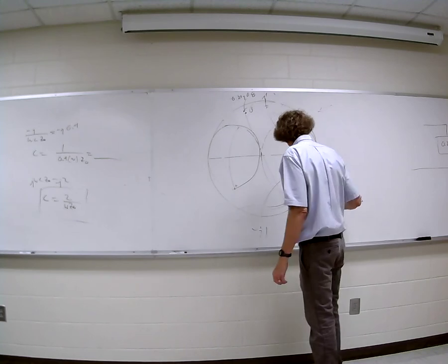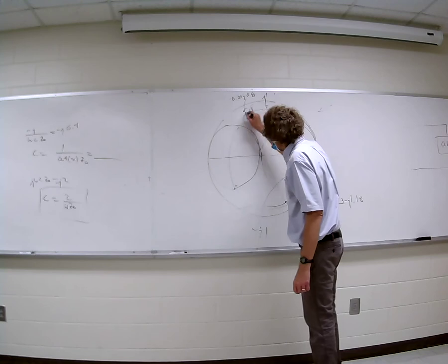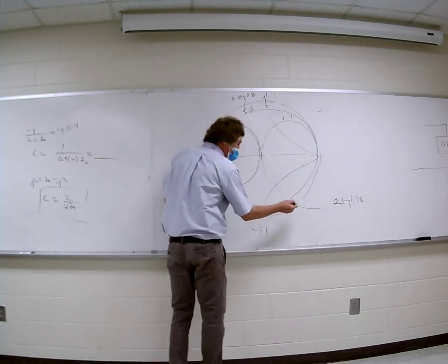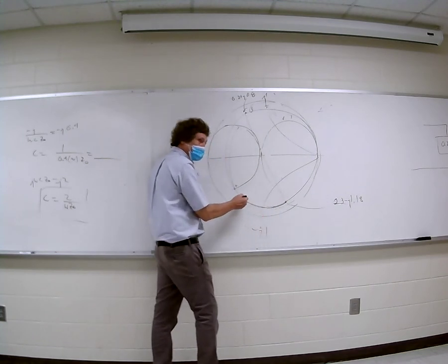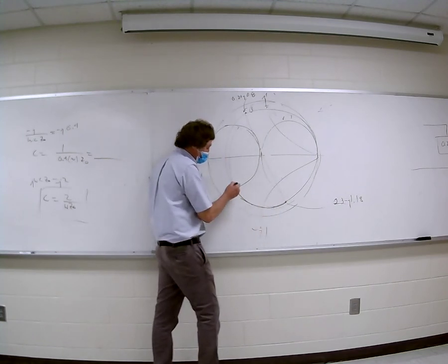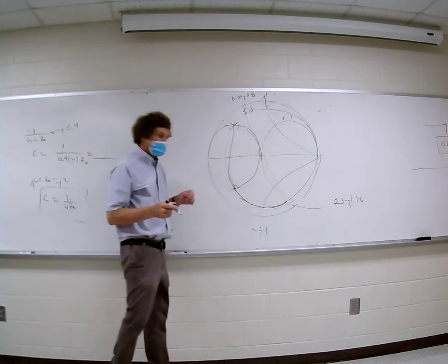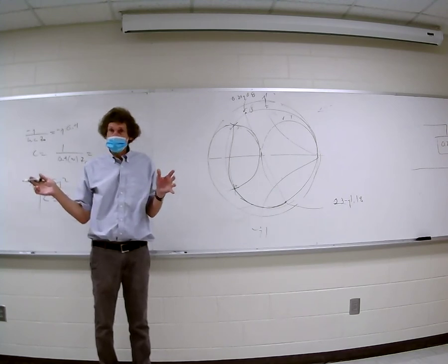So when I'm in the admittance domain here, I travel along this trajectory. If I'm adding plus j something, well, first let me ask you this. If I go on the 0.3 trajectory, which is going to be something like this, so if this is 0.3 minus j 1.1, this is 0.3 real, right? There are 2 points that intersect this rotated circle, right there and there. Do you agree with this, class? Go ahead and draw it.